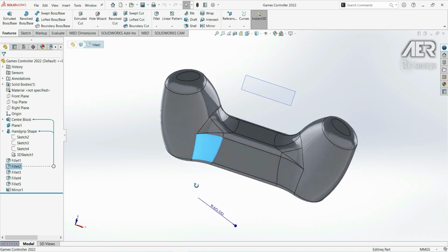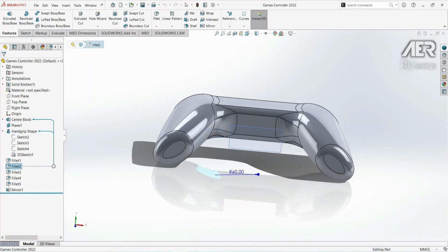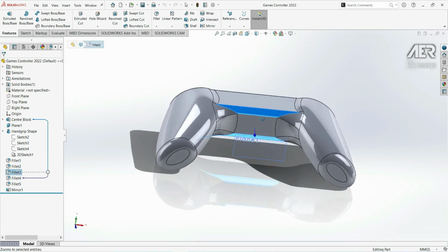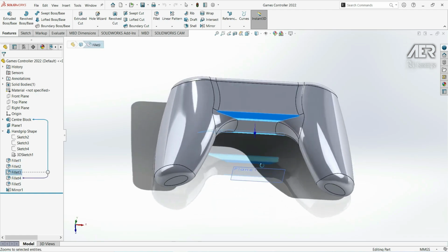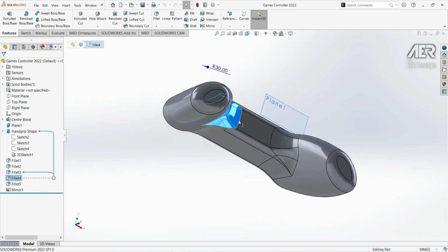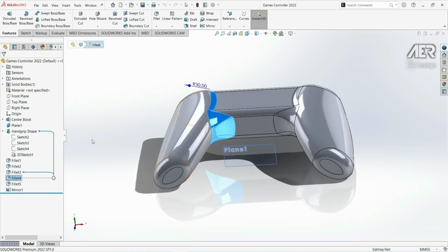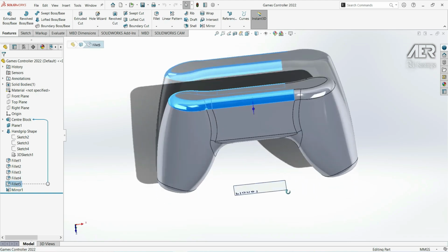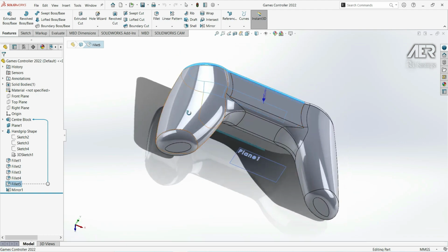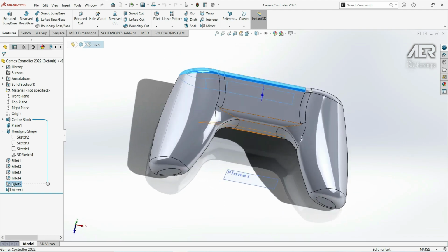And if you've got a cap there underneath, and then you can't add that fillet, then try to go back into the loft feature and adjusting the guide curves so you don't have a cap there. And then you should be able to add the fillet, and then we rounded off the rest of the corners. And we just mirror the entire body over. So we use the bodies to mirror instead of features to mirror. And now we've got our game controller shape.